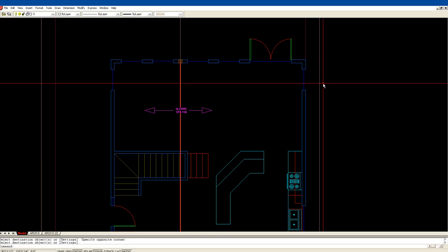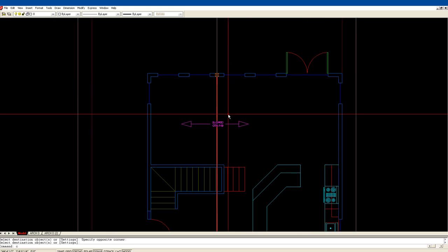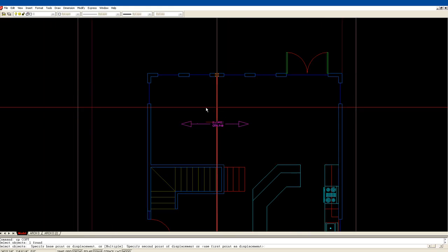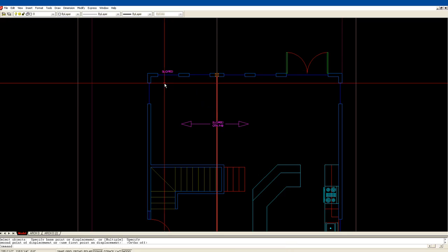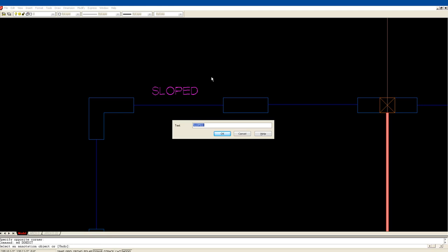Okay, now we have to tell them what size these windows are. So we're going to steal some text. Okay, so if you've downloaded the font and put it in, you'll have this font. Okay, when we do windows and doors, when we're labeling, we always label width first, same as room sizes and all the rest of it. Always width first in construction. And we work in feet and inches.